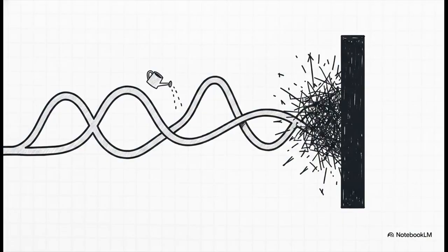Now, we should definitely note that modern software-defined radios, or SDRs, handle this third-order distortion quite differently. Instead of that classic, predictable 3-to-1 slope we just talked about, the analog-to-digital converters in SDRs can exhibit unpredictable, roller coaster-like distortion as signal levels rise. Eventually, they hit an absolute clipping point that produces harsh, broadband noise rather than those discrete ghost signals.